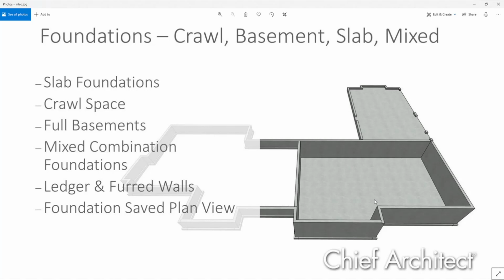Great. Thanks. Hey, so on the foundations, I have a question, and I also wrote that in, but the pre-questions had just limited area to type my question in, so I kind of abbreviated it. In this part, I generally do slab on grade, which has beams, like a waffle slab would be my best example. Perimeter beams are 12 inches by 36 inches, plus or minus. And then there are interior beams of similar size, and then there's like a 5-inch slab that goes with it.